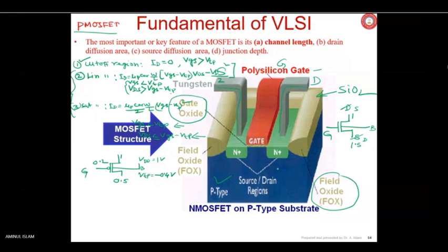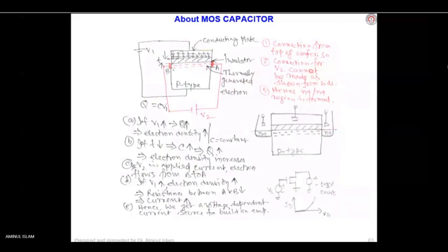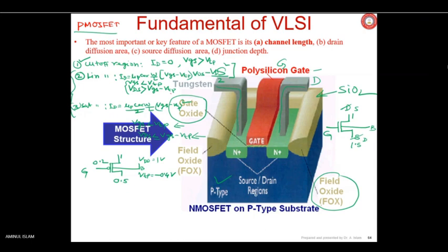If you think of the flow of carriers, say electrons are moving in this direction, so this one I can say is source and this one is drain, with current in the opposite direction. Source means it is sourcing the carrier. That way you remember. In case of MOSFET, the negative terminal of the battery, or lower voltage, wherever lower voltage is, that will be the source, because in this case the carrier is electrons, so electrons will flow in this direction. You can think of that. Let me regain the earlier values, otherwise you'll be confused.